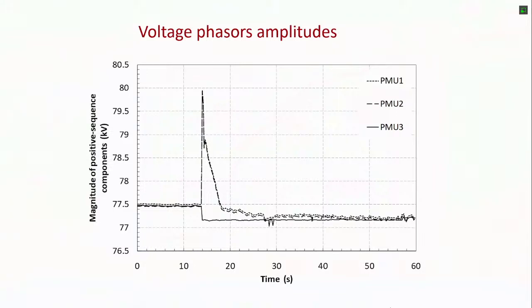Yes, it is, because in the PMU there is a filter at the beginning, there is a trick in order to not be disturbed. There are harmonics, so you need to identify the first component, the 50 Hz, from a waveform that also contains some harmonics and some disturbance. Yeah.